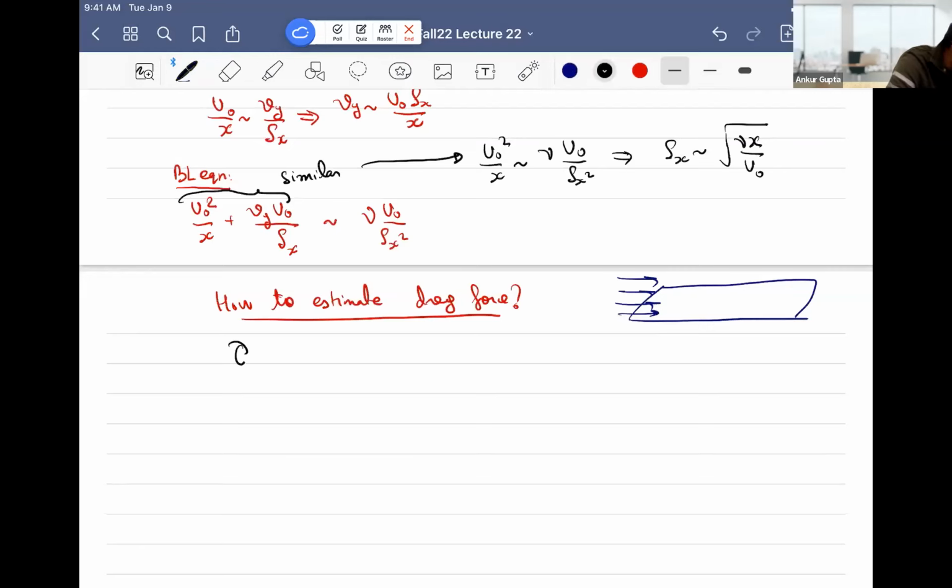And what we will want to estimate is a tau normal to x, so normal to y and parallel to x, and that is equal to, and this is sometimes simplified further, mu times del v x by del y plus del v y by del x.